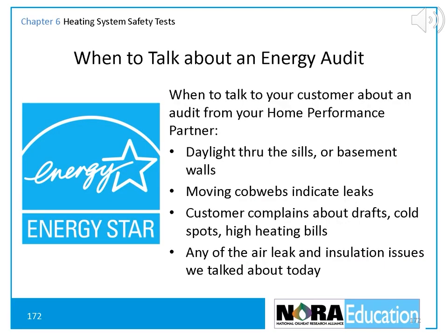Other things that indicate that there's a problem in the house could be daylight you can see through the sills or basement walls. In other words, if you can see daylight through the walls while you're standing in the basement, those are probably big leaks. Moving cobwebs, blowing back and forth inside of a cellar, indicate leaks. Customer complains about drafts, cold spots, or high heating bills. And finally, any of the air leaks and insulation issues we've talked about today.